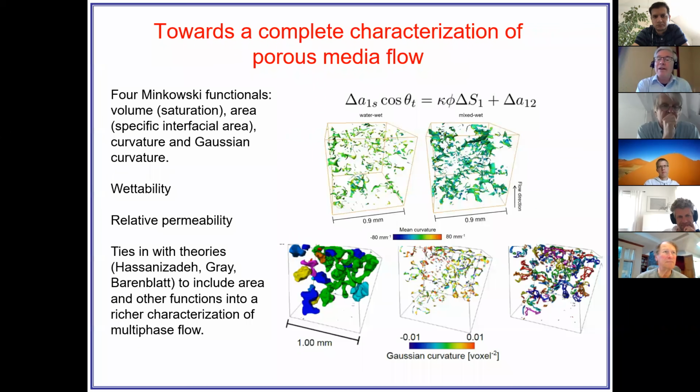In this gas diffusion layer, you wanted the gas to go in and the water to come out. Looking at this, you want minimal surfaces. You want something that's mixed wet. Do you know how they make these gas diffusion layers? They have this fibrous material that's naturally water wet. They coat a fraction of those fibers in basically an oily coating, a plasticky coating. And so some bits are oil wet or actually water repellent, so they don't like water. Some places attract water, so they're water wet. So empirically, in the design of these gas diffusion layers, they've made a mixed wet state.